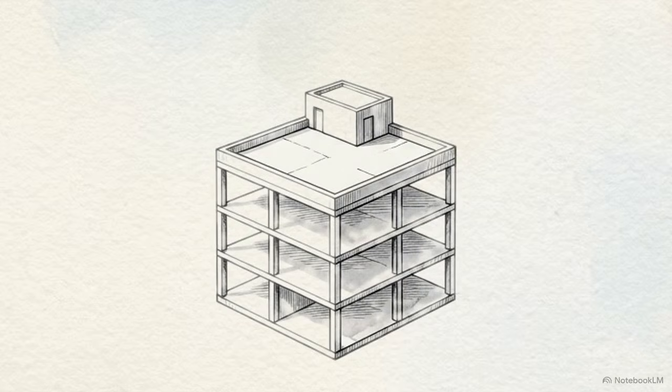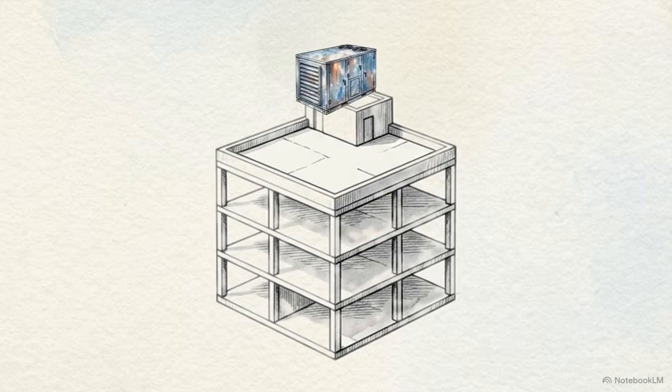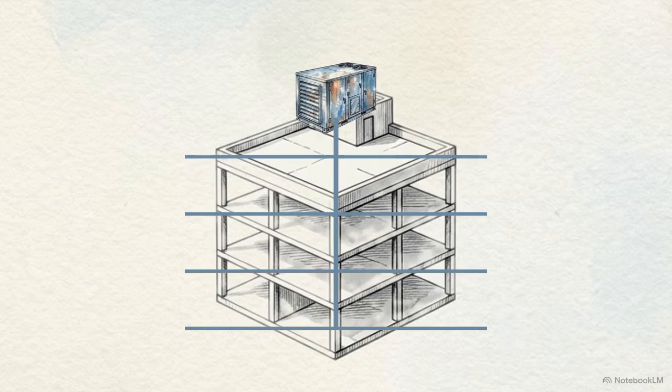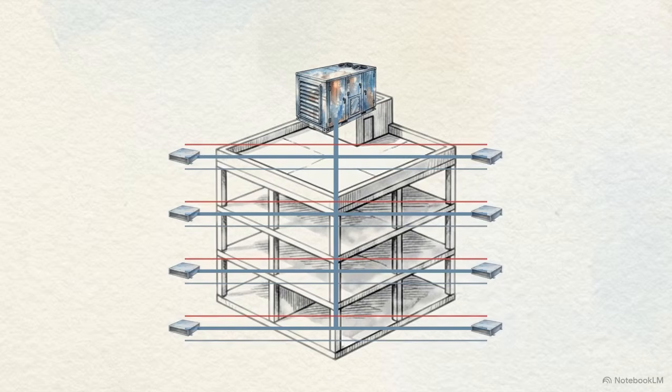Now we can synthesize these elements into a unified model of a high-efficiency commercial building. This wireframe animation shows a DOAS unit dropping onto the roof. It intercepts and strips the latent moisture loads from the outdoor air, sending dry ventilation down to the floors through blue shafts. Next, we layer in the VRF network to handle the sensible mass flow.